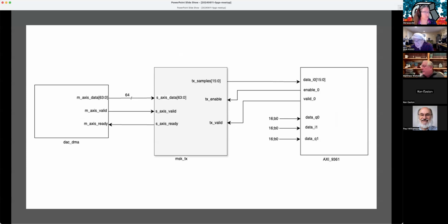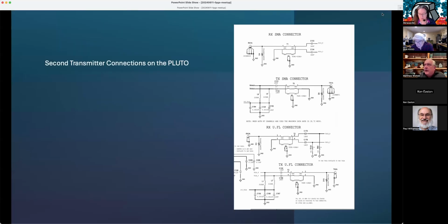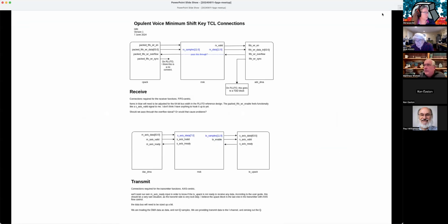Yeah, and for the receiver simulations, I had a PRBS on my test bench, which was not matching, but I have just an XOR in the top level that I'm also looking at, and there was a burst of bit errors a little bit into the simulation, likely due to the timing loop stabilizing, but it was clean after that. So I think the RX is actually in pretty good shape too.